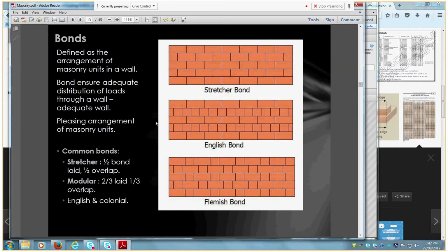Whereas with the cavity brick, and I'll show you in the slides further on, you can fit your insulation in between here. That's typically done with wall ties with little wheels on there to hold it back to the internal leaf, so it allows moisture to seep down the inside face of the external leaf and exit without going into your insulation.